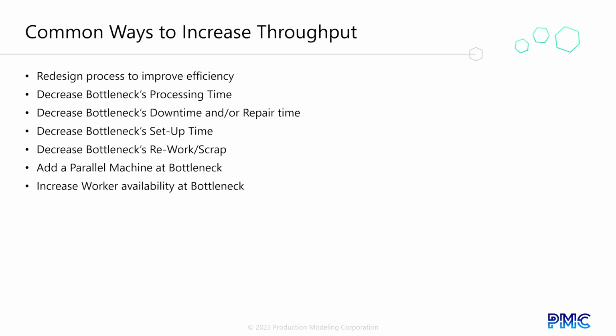If the bottleneck stations require workers, you may be able to speed things up by adding another worker to a shift or adding a part-time shift with fewer workers. Similarly, you might be able to increase throughput by increasing buffer size. If your process includes the production of different models or types of products, then changing how they are scheduled may increase throughput. Plant Simulation is the perfect tool to help you to not just optimize your system through what-if games with the above possibilities,